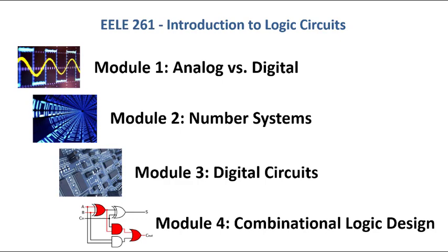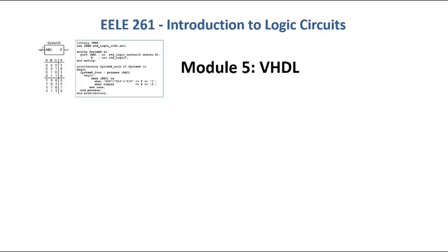Then you immediately run into the situation where the circuits that you build become very large very quickly. And the pen and paper approach that we learn in Module 4 becomes impractical for large circuits. So we have to change the design methodology that we use in digital systems to one that is more hardware description language based. You can think of this as typing out the description of the circuit that you want, and then we allow a computer tool to synthesize the circuit for us, and then we can take that circuit and build it in hardware.